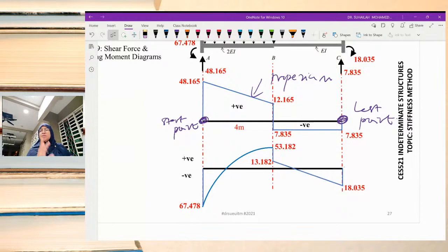So these are the two formulas. For an indeterminate beam, we calculate using the stiffness method. The procedure is all the same except two parts. In the main diagram, we don't have to label coordinates. We don't have to put arrows.